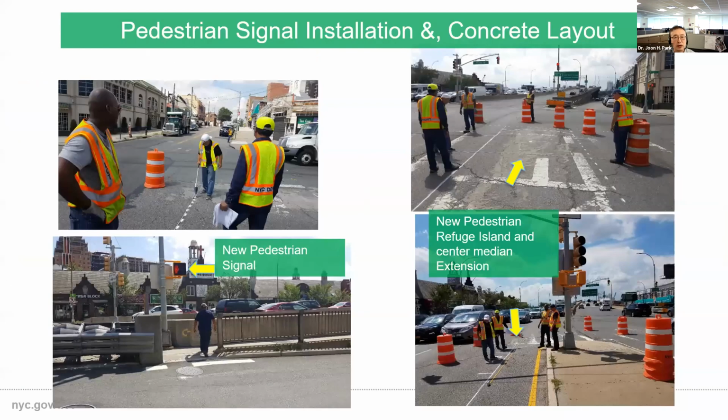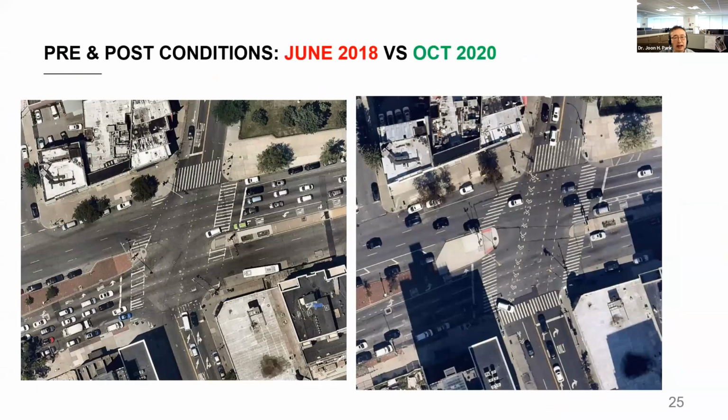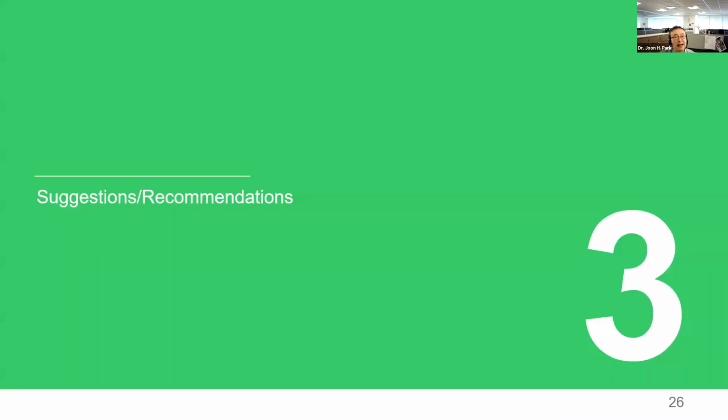So this portion is extended, at least they can connect all the way down to the other adjacent intersection that can continue to cross. And then it minimizes the conflicting turning vehicles using the split LPI signal timing, also provide a bike lane situation. So finally, we have some suggestion and recommendation.